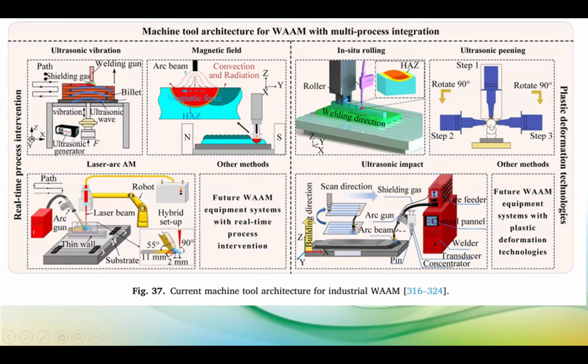Here, even with a controlled wire feeding system, we cannot achieve the correct composition. We cannot achieve the expected composition on the bottom substrate because the welding arc is a highly unstable thing.